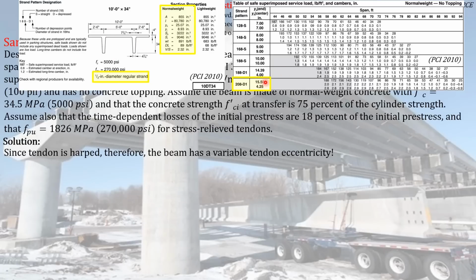So again, the values that you are seeing here for the specific strand pattern that we assume are not the specific eccentricity of the pre-stressing reinforcement, but the distances of the pre-stressing reinforcement with respect to the bottom. So you have to be careful with that.